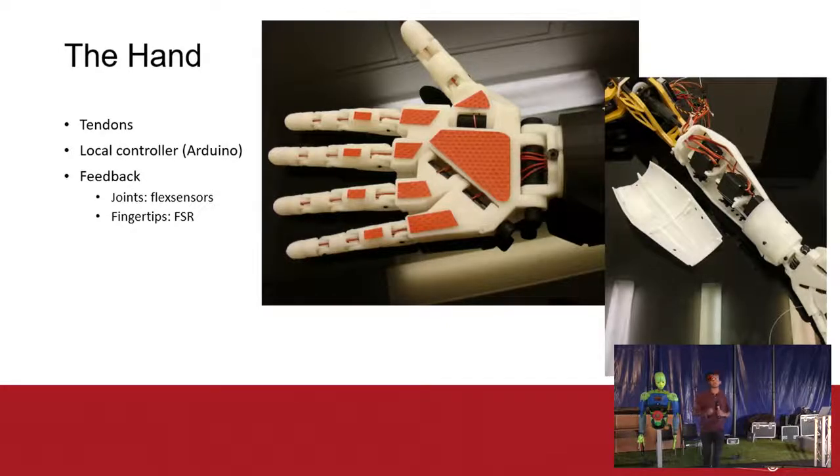The human hand can control different joints. So you can close your distal joints without closing your proximal joints, or you can close the proximal joints without closing the distal joints. If you're only using one motor per finger, like the original design, you wouldn't be able to do that. But if you have an Arduino in the forearm, you will probably need to use smaller motors in that case, but you will be able to use more motors because you wouldn't have to run all these wires up to the Arduino that originally was controlling the whole robot.